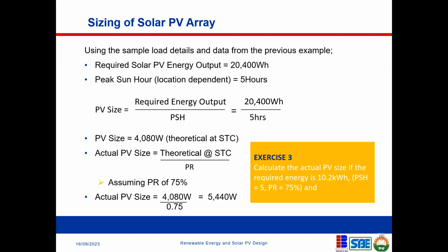Yes, I was coming to that question actually. And in addition to that, I also want to ask, given that this capacity we are talking about from our initial sizing is a 3 days capacity, and then the peak sun hour that we're talking about is a daily peak sun hour, so why do we have to generate all this when we know that tomorrow again we are going to have 5 hours, next tomorrow we are going to have 5 hours? Is there anything that can guide us in doing a more economical design, since we know that we will continue to get this sun on a daily basis?